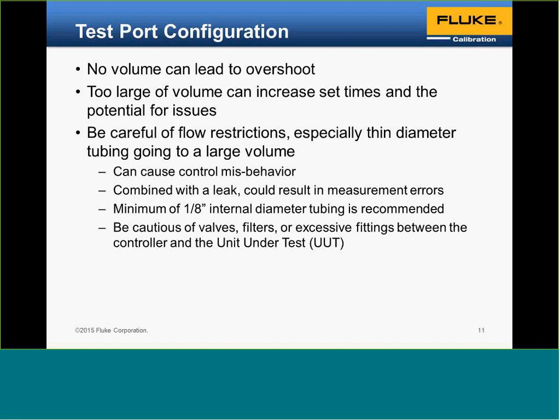Another consideration on volume is that it's preferred to be relatively constant in volume. The concern here is a scenario where you have a valve in the part of the instrument that you close to decrease volume, perhaps where it's just the pressure line, then open the valve and now a large volume is filled.